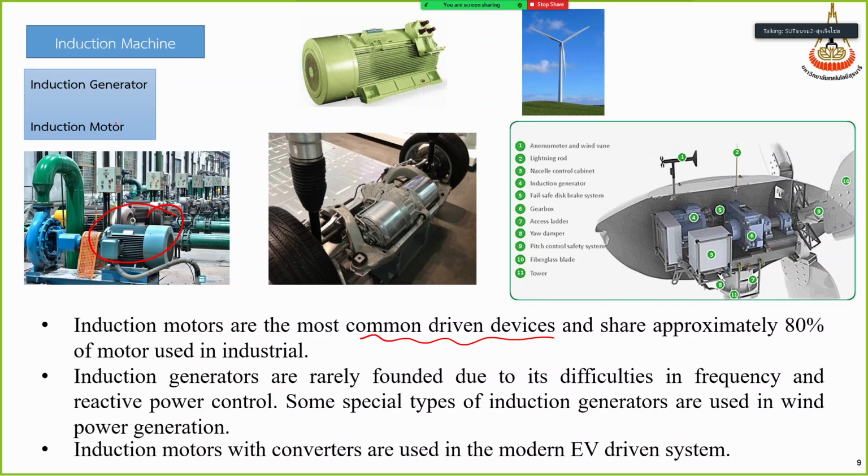Okay, and induction generators are rarely found due to their difficulty in frequency and reactive power control. Maybe we find this type of generator in wind turbine generation, where they use a very special induction generator. And even in the EV car.